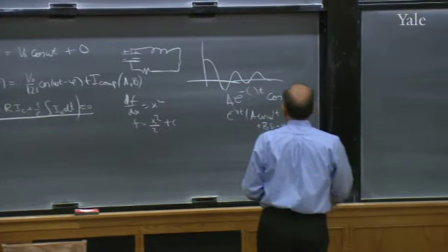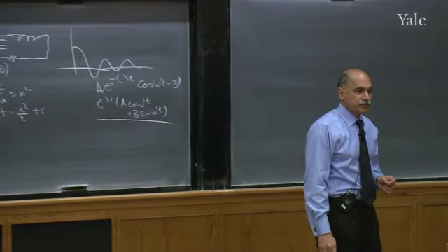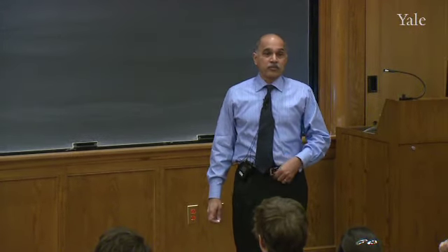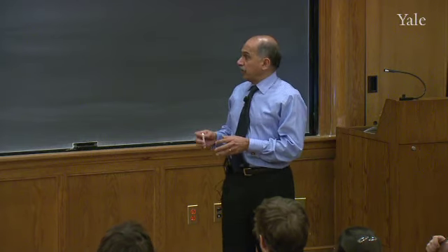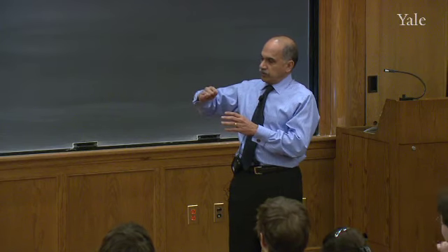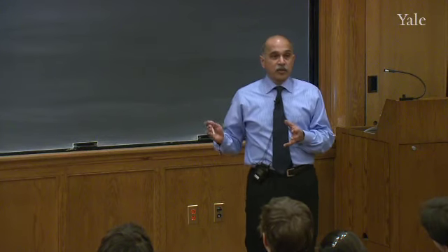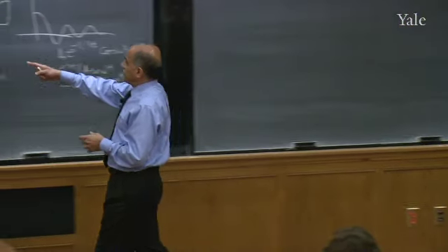But we don't usually care about this guy. Do you know why we don't talk about this too much? Yep. It dies off exponentially. So in real life, it doesn't matter. If you really want to know what's happening, in other words, take an LCR circuit, take an AC source, put a switch, open, keep the switch open. The minute you close it, current will be 0 by continuity. Current cannot jump. So this function obviously is not the whole answer.